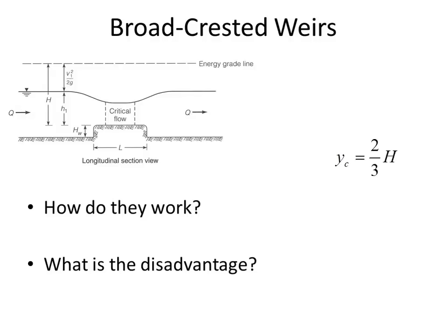It's because maybe it would be critical over here, but some of the flow would be diverted around the obstruction, and there wouldn't be a uniform flow per unit width. You maybe would know the lowercase q here, but you'd have a different q here versus there. So it would cause imbalances in the flow per unit width spatially across the width of the channel.